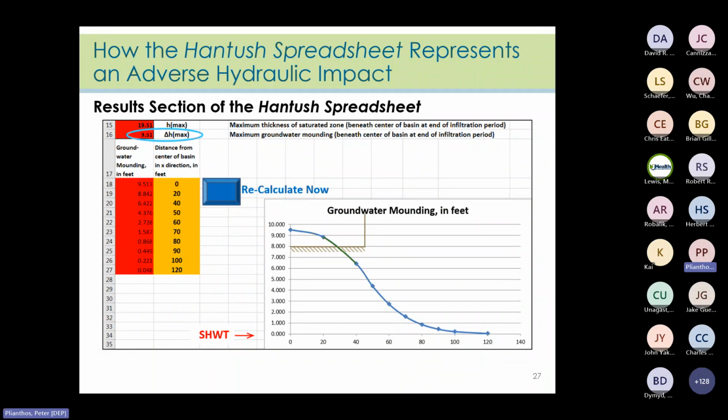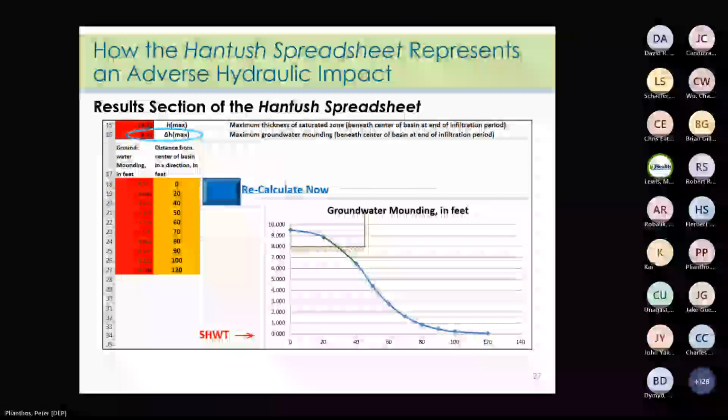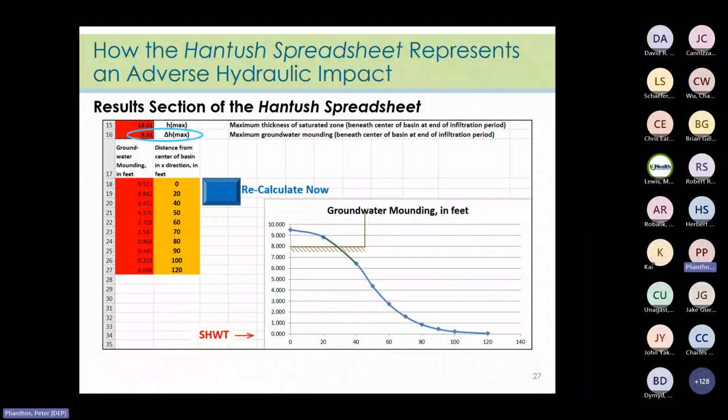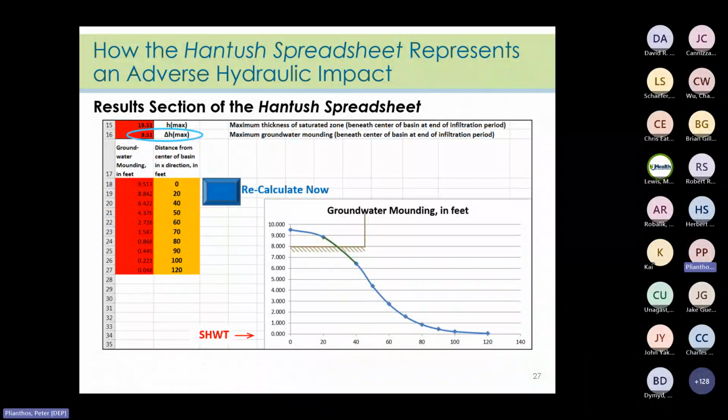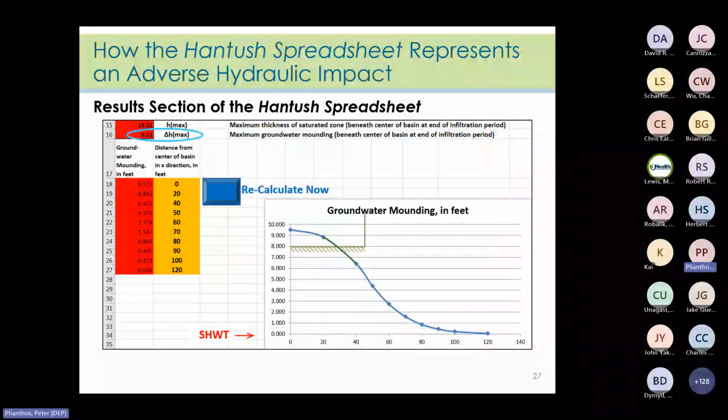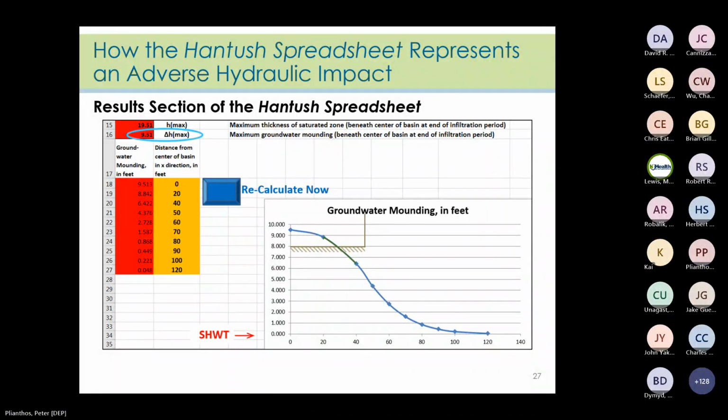To do that, we have to reduce the value for R. We don't know exactly how much it will slow, but my first attempt would try reducing it by 50%. However, we are not ready to click Recalculate. The horizontal hydraulic conductivity is not adjusted since it is not affected by the reduced hydraulic gradient in the vertical direction. But the duration of infiltration period must be proportionally adjusted to reflect this slowing down. For example, we will double the initial value for T if we halved R.